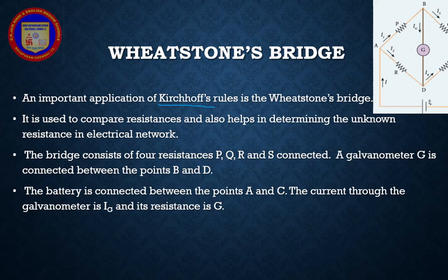An important application of Kirchhoff's rule is the Wheatstone bridge. It is used to compare resistance and also help in determining the unknown resistance in an electrical network. The diagram is shown over here. The bridge consists of four resistors P, Q, R and S connected as you can see there. A galvanometer G is connected between the points B and D. The battery is connected between the points A and C, and the current through the galvanometer is Ig and its resistance